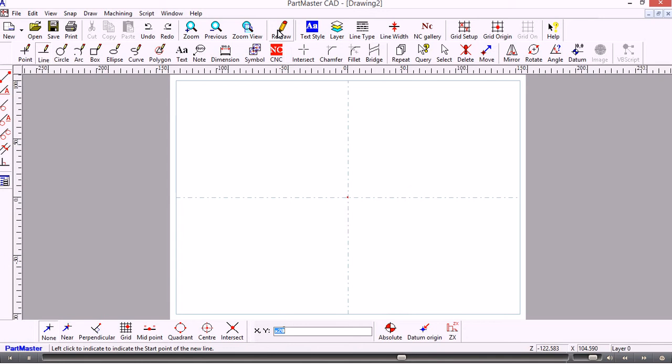You can also use this to draw lines for a lathe. Of course if you prefer to work in Z and X, then you just simply click this button here, so that's active. Now the lines are taken from the Z and X rather than XY. But if you work in X and Y, you can always just create a profile, and when you get into turning, the system will automatically go into Z and X, so you don't need to draw in Z and X, but some people find it easier to do so when they're working from a drawing on a lathe.